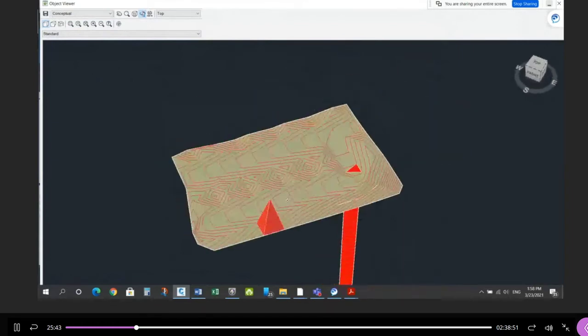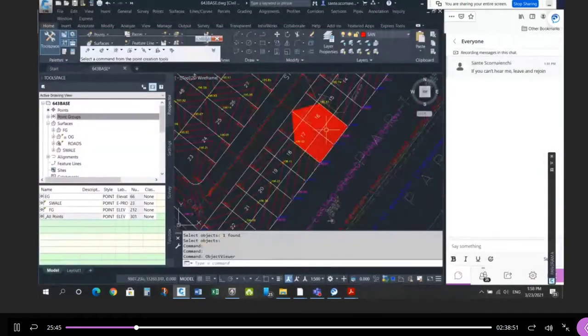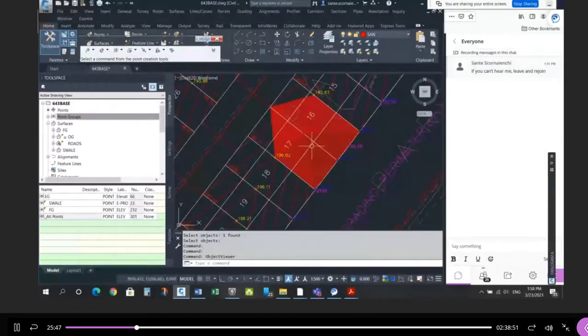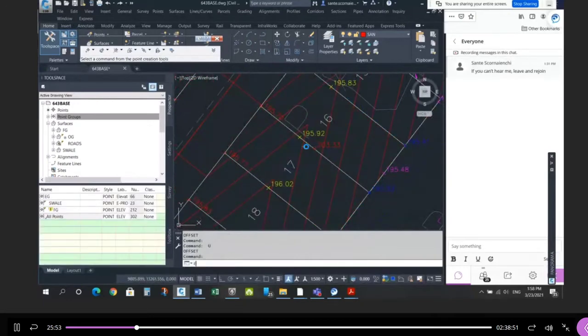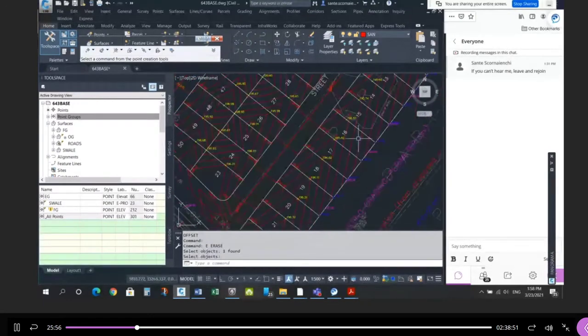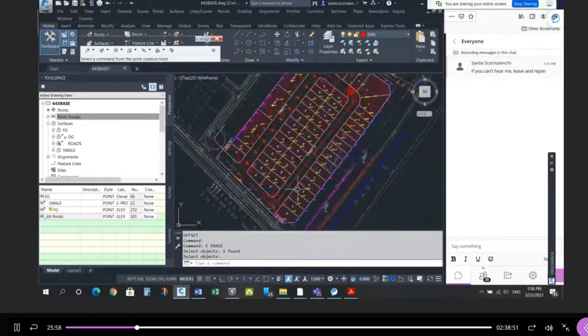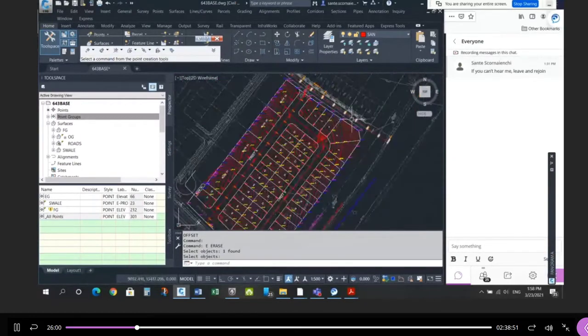And you might see a little bit of a problem. And you can also tell by the density of contours and so on. Okay, so that's another common mistake, to use a slope instead of a percent grade. And it makes it steeper. Okay, so that was another common error. So those are the general things to look for.